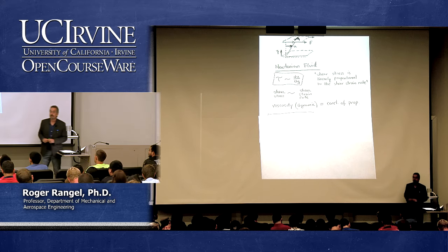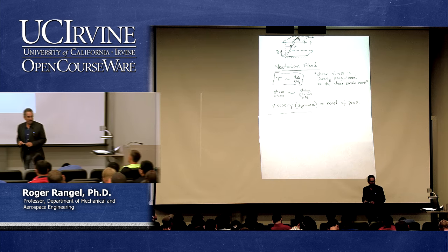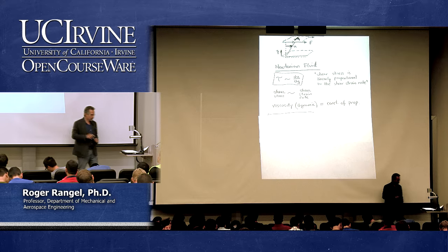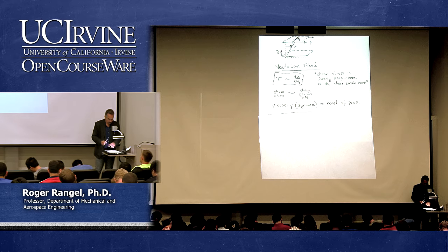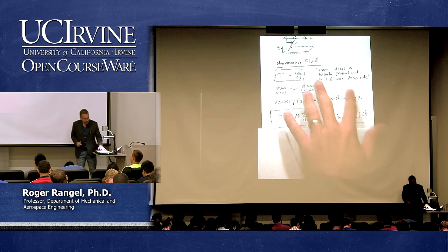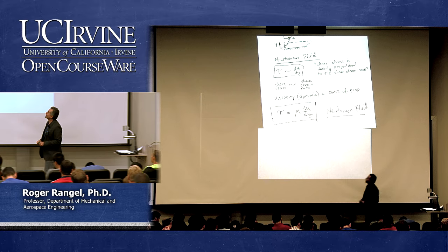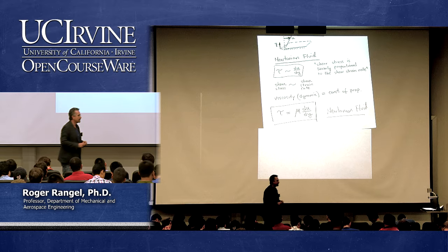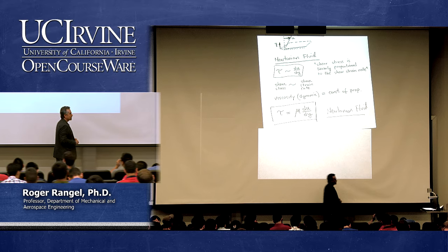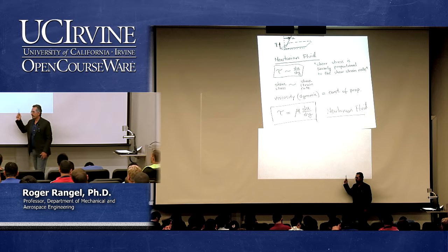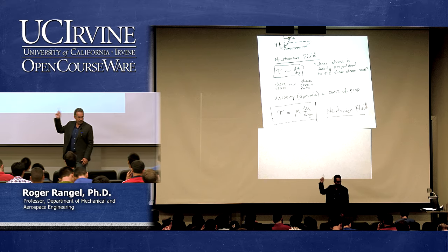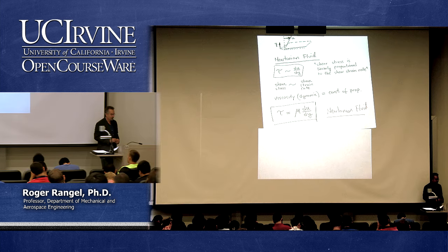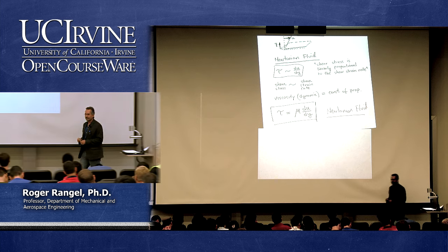So the viscosity, we also refer to it as dynamic viscosity, because there will be another viscosity that we'll talk about. So the so-called dynamic viscosity is the constant of proportionality, and therefore the relationship that I'm looking for is right there. Shear stress equals viscosity, which is the constant of proportionality, times shear strain rate du dy. If a fluid satisfies that law, follows the behavior described by this law, we call it a Newtonian fluid. Very easy.